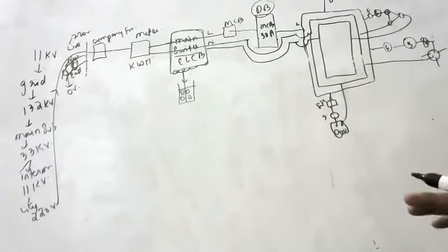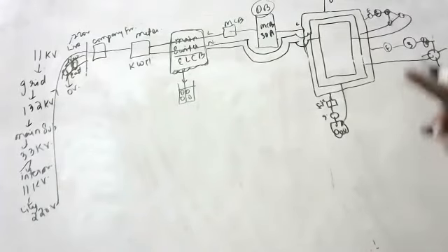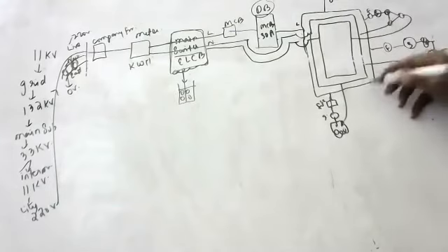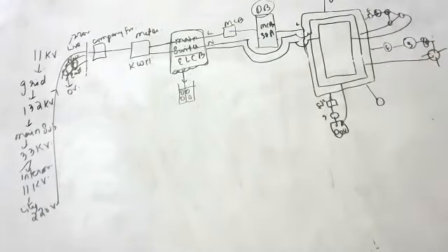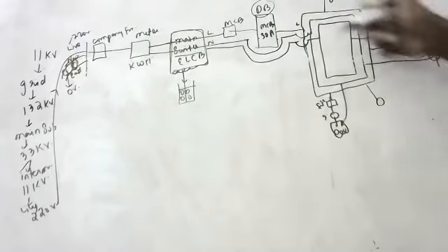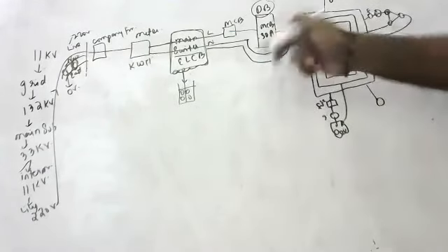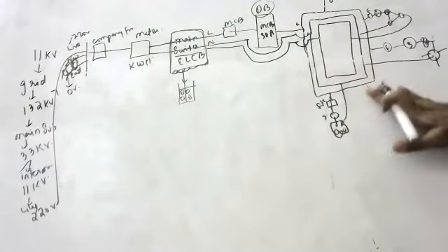For each appliance, the wire used for connection should have proper current carrying capacity. Sir, in this room, if I put one more instrument, will anything happen? Nothing will happen. But the total current of all the appliances in this portion should not exceed 30 amperes. If it exceeds, you have to put an extra MCB, remember.